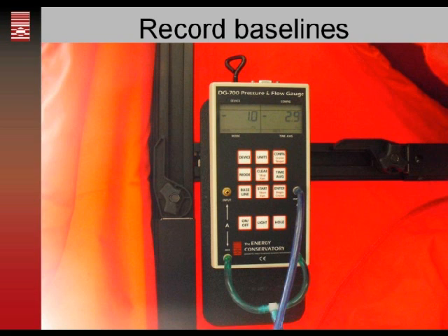So now we've got our blower door sealed. We've got the rings back on the blower door. We're in the pressure mode. We've used that splitter that came with your DG700 gauge, the T connection with the two short pieces of hose, and we've connected that on the reference taps on channel A and channel B. So we've got our hose to the outside connected to both channel A and channel B. If you don't have one of those T's, you can run a second hose to the outdoors.